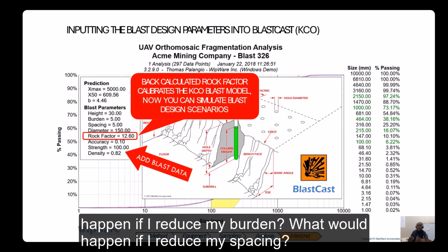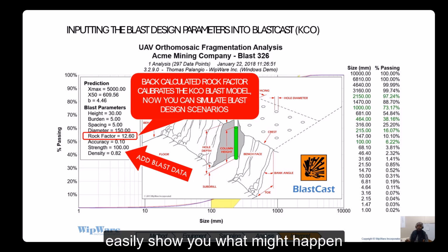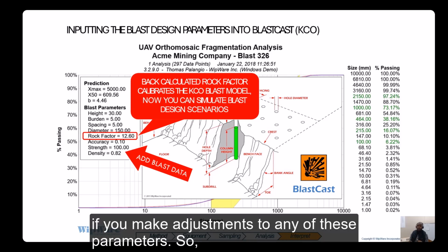What will happen if I reduce my burden? What will happen if I reduce my spacing? What will happen if I change my bench height? So the software can easily show you what might happen if you make adjustment to any of these parameters.